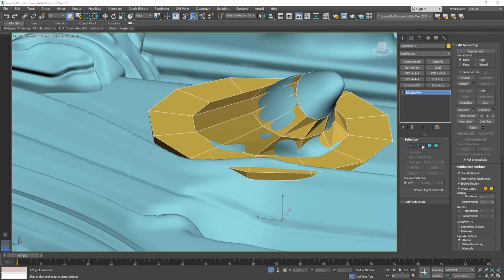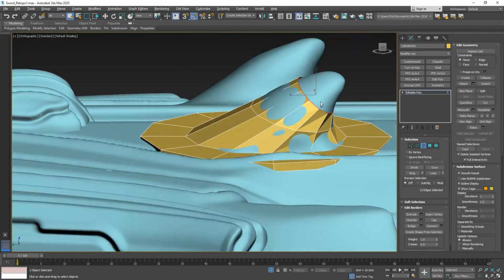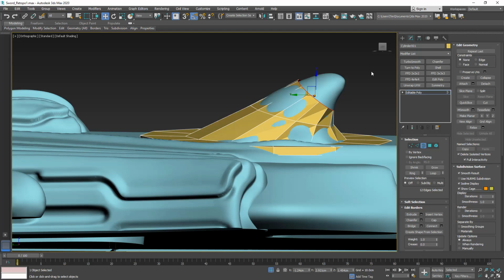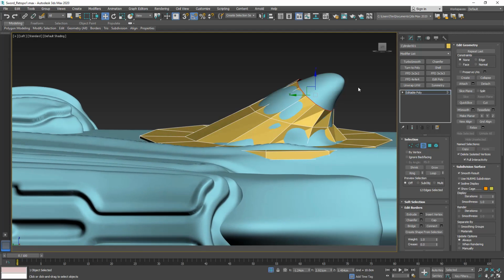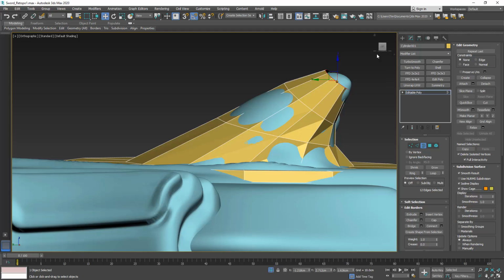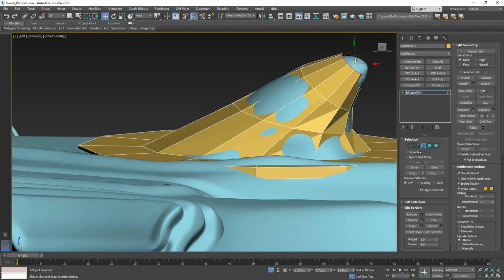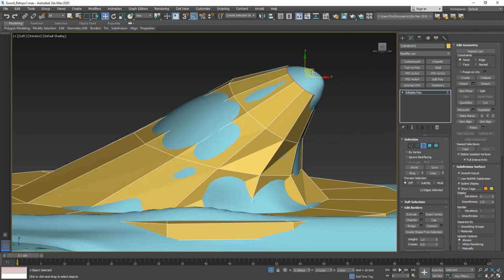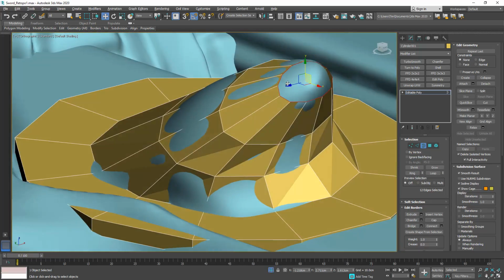Remember to press F3 to go see the wireframe mode, which can be quite useful to toggle every once in a while. And I want to go back here in the left orthographic view and drag out another loop. So now I'm just going to go over here to our scale tool and pretty much scale it so that it fits, move it a bit here on the x-axis, and here on the left it looks like we can drag it down a bit more.